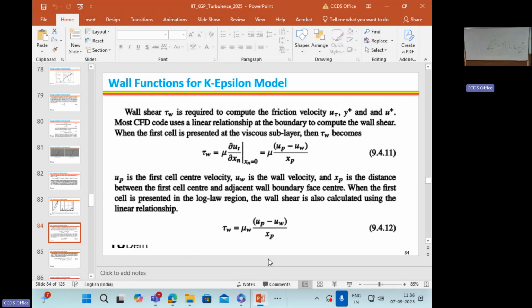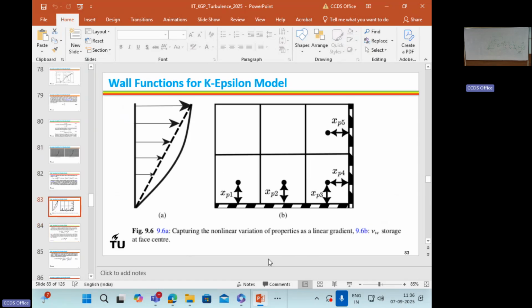This holds if the distance between the cell center and the phase center is extremely small. But if it is higher, what to do, right? If it is higher, we use the same formula, but instead of the dynamic viscosity of the fluid, we put some wall viscosity or friction viscosity, the turbulent viscosity. This information will be saved at this phase, because suppose this cell is at the corner. It has two different phases. One cell is connected to two phases.